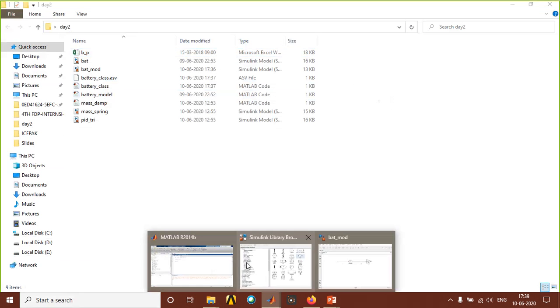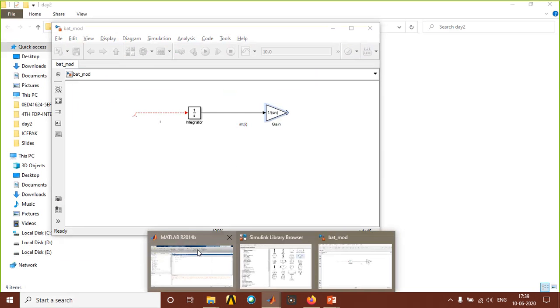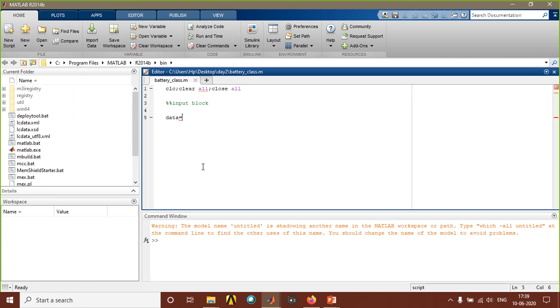So how to bring that Excel sheet in? Go to MATLAB: data equal to, the command is xlsread. Open bracket, put apostrophe, then put in the name of that particular file. If you put a wrong name, you will not be able to open it. So just simple: data equal to xlsread, the particular name of the file. Abhinash, some of the details will be available on the net. Some of the things may not be available, but this particular model we will give you.